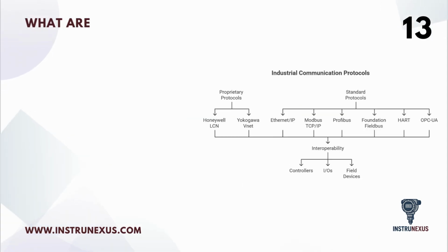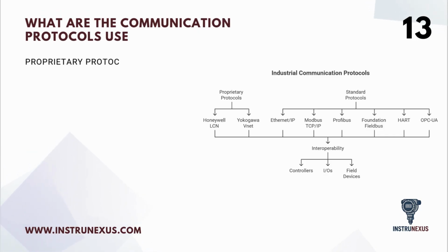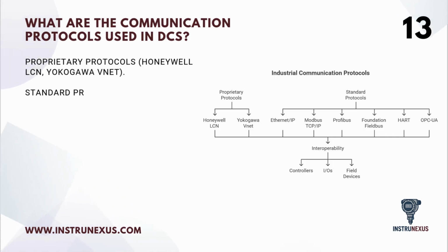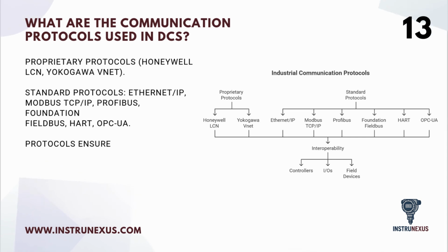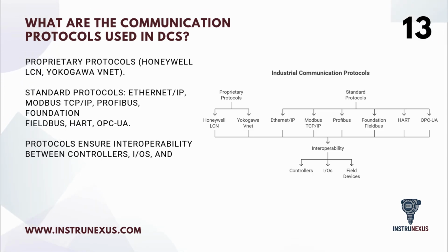What are the communication protocols used in DCS? Proprietary protocols: Honeywell LCN, Yokogawa VNet. Standard protocols: Ethernet/IP, Modbus TCP/IP, Profibus, Foundation Field Bus, HART, OPC UA. Protocols ensure interoperability between controllers, I/Os, and field devices.